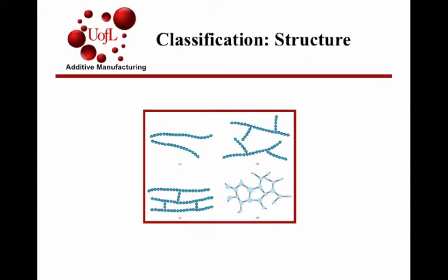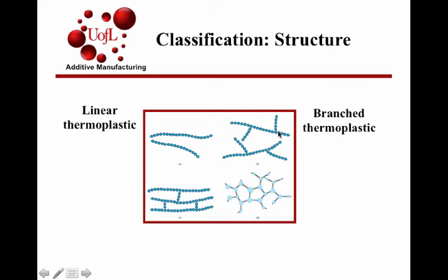In addition to molecular weight and crystallinity, you also have chain configuration that can be controlled by polymer chemistry. You have an example of a linear thermoplastic. These chains are completely straight, squiggly lines or straight lines, but on the other hand, in B, you have a branched structure where you have monomers that have been synthesized off the main chain as well. So these represent different ways and different resistance to crystallinity as well.